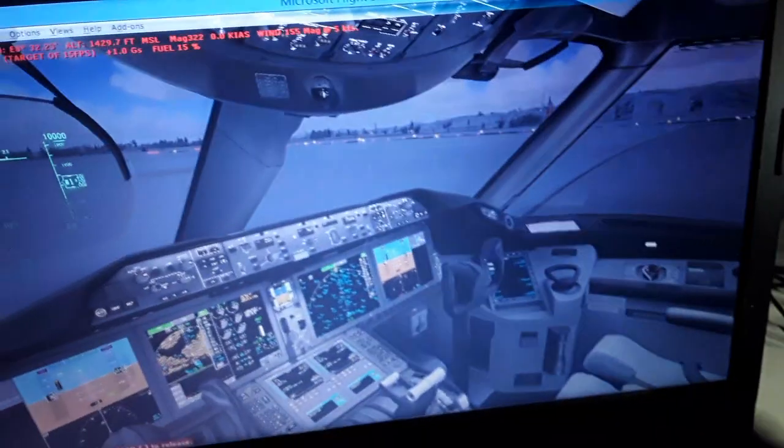The flight management computer is going to calculate the horizontal stabilizer trim, the elevator trim position, for takeoff, climb, descent, approach, and landing. We can set the auto trim automatically. So we have 4.25 degrees automatically for takeoff, with 15 degrees of flaps extended. Using runway 14 at Zurich International Airport, LSZH in Switzerland, we're going to have the runway length and slope, the wind direction and speed, the barometric pressure, the density of the air, and the temperature of the air.